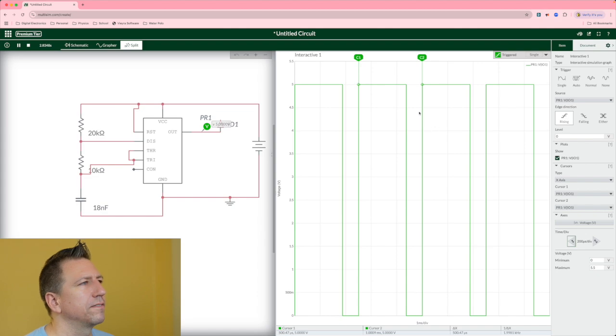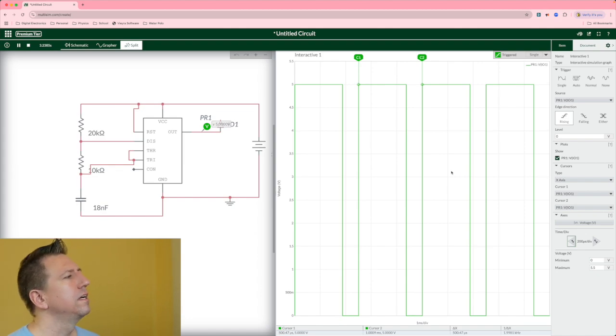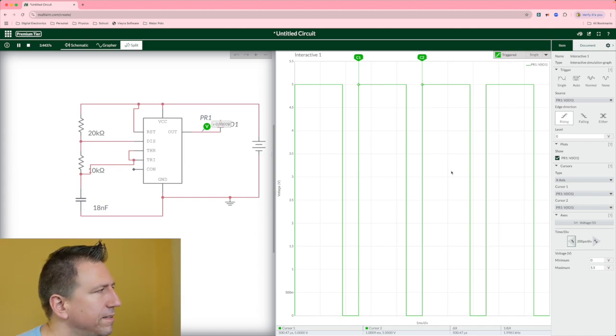Furthermore, we are looking for a 75% duty cycle, and just by eyeballing this, I can see that if we're not exactly on, we got pretty close to 75% right there. And so that's how I wanted to show you that we could design a 555 timer without knowing its internal operation, just knowing that we have R1, R2, and C, and we have some design equations that go with that, and we can use those design equations to generate the frequency and duty cycle that we're looking for.